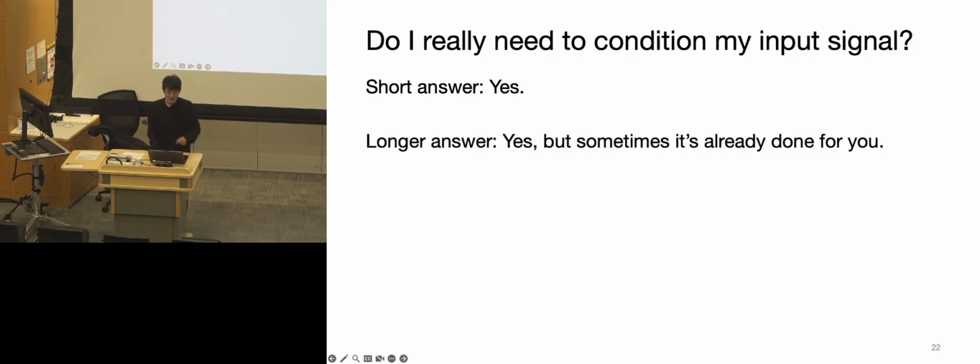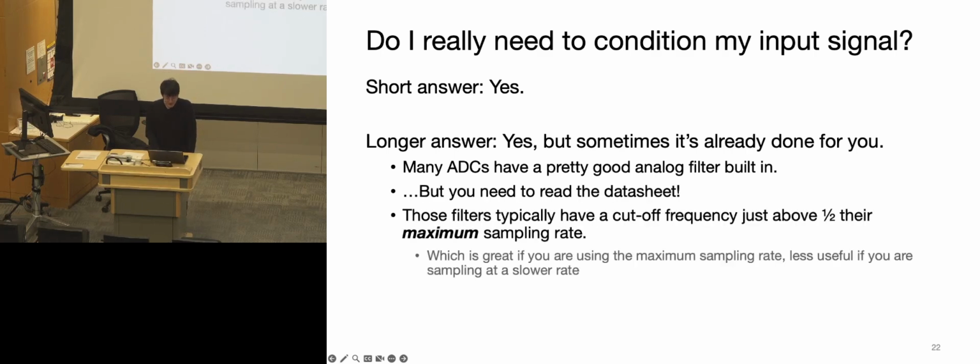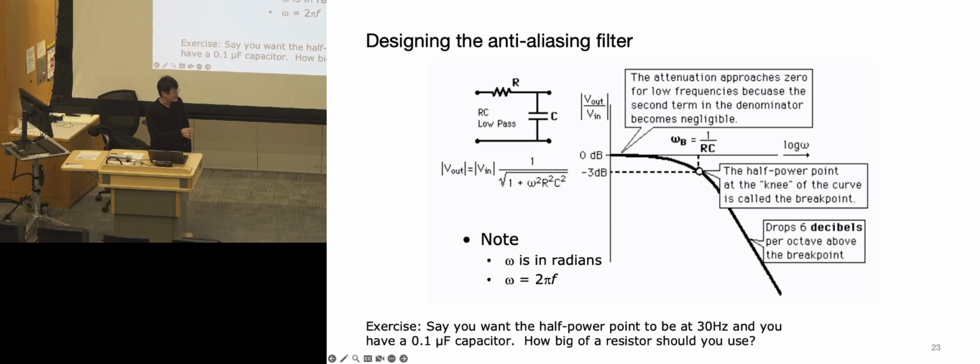And do you need to condition your input? Which is what we're trying to do here. It's still good to have, although most ADC channels have anti-aliasing functions built in. There's a few reasons for that. One of the reasons is hardware being hardware.